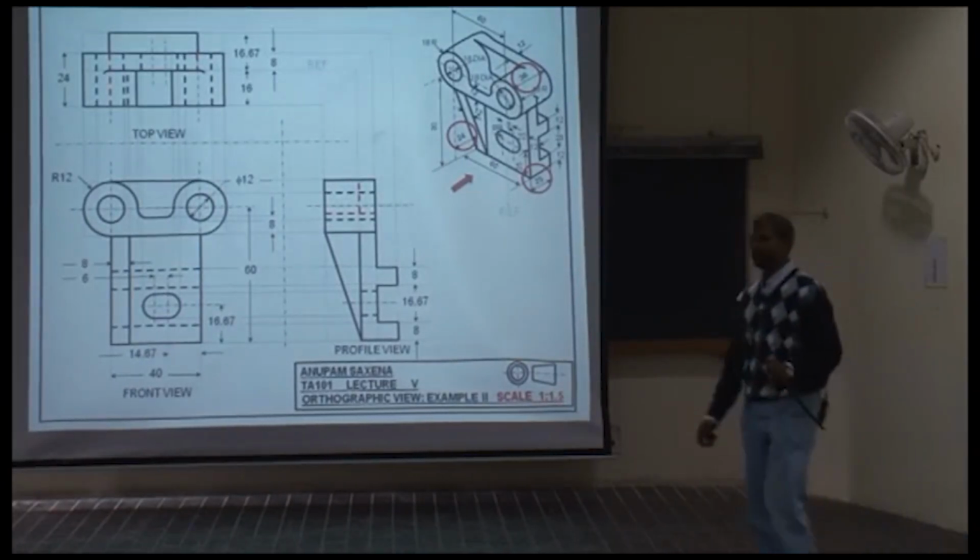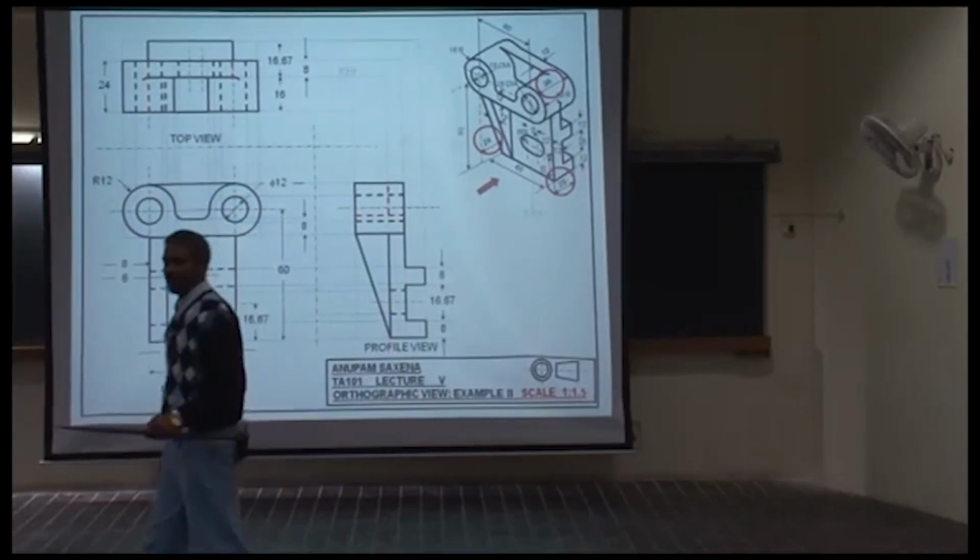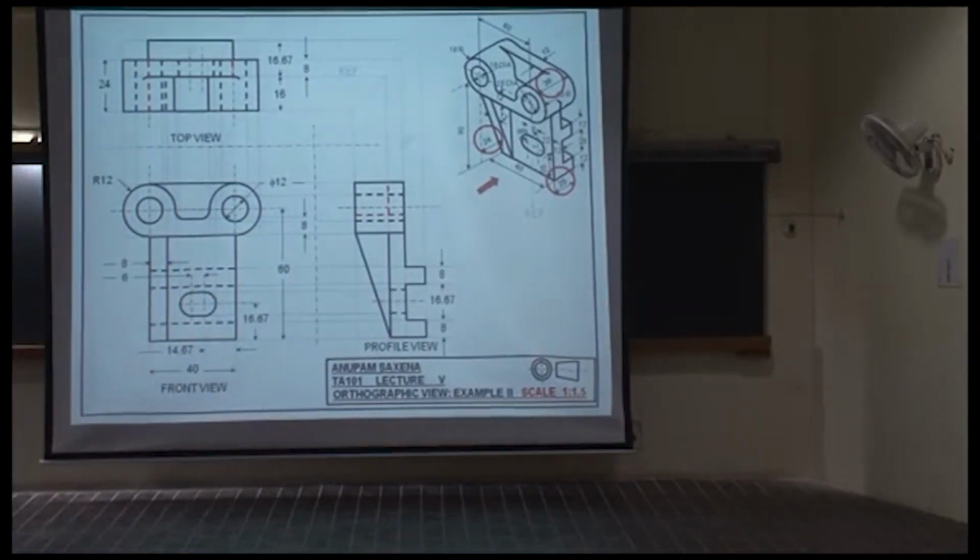So when you're drawing these orthographic views, you need to be very, very careful. One way to practice or exercise care is to ensure that each and every feature in each and every drawing is related by the corresponding projection line or the construction line.